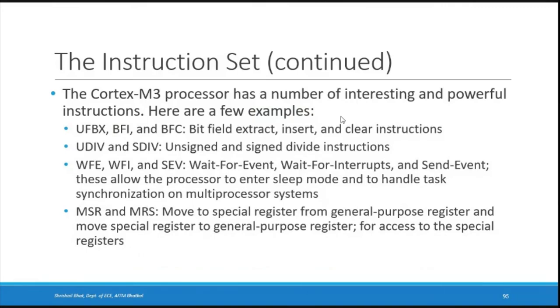Some examples are UBFX, BFI, BFC. They are bit field extract, insert and clear instructions. You can extract certain bits. You can insert certain bits in between the register. You can clear certain bits. Then divide instructions, unsigned and signed divide instructions.